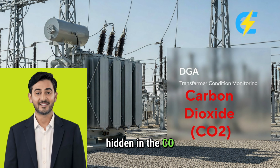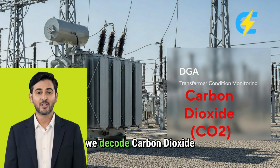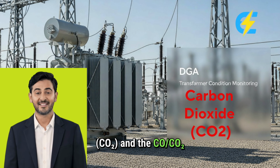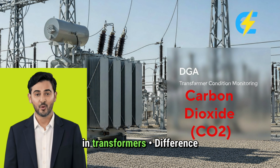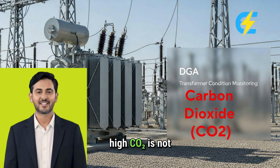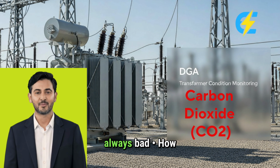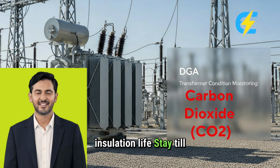The real truth is hidden in the CO-CO2 ratio. In today's Electroverse episode, we decode carbon dioxide, CO2, and the CO-CO2 ratio. Why CO2 is always present in transformers. Difference between healthy aging and accelerated aging. Why high CO2 is not always bad. How the CO-CO2 ratio reveals insulation stress severity. What ratio values mean stable aging versus active damage. And how senior engineers estimate remaining insulation life. Stay till the end, because CO2 does not talk about faults.